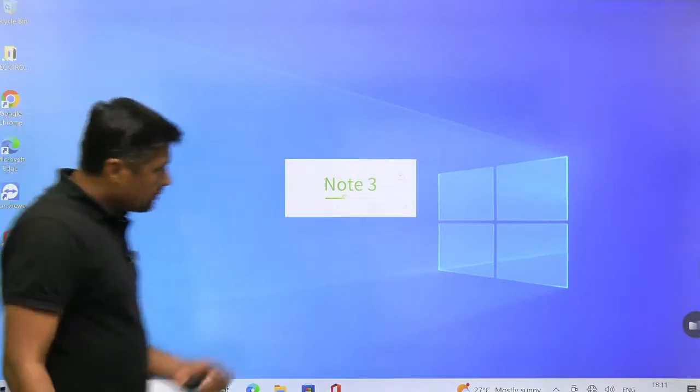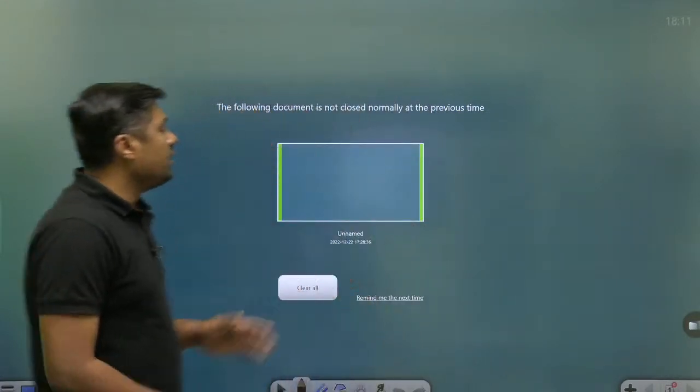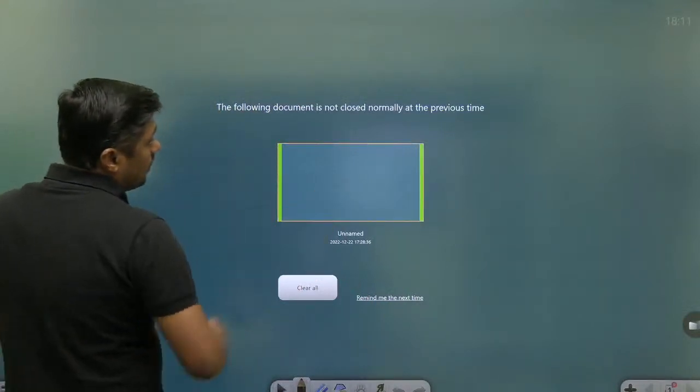While this comes on, what do you mean by the voltage doubler? In a voltage doubler, first of all, we apply a rectifier with a capacitor filter. At the output side, that circuit is called a peak detector, positive or negative. At the input side we connect a clamper, positive or negative. In this way we design the voltage doubler.